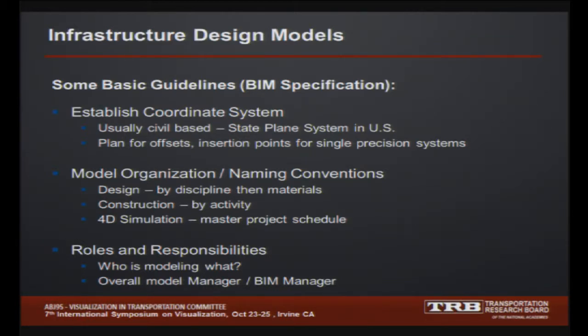Model organization is key to get established up front. Naming conventions. Is it a design model? Is it a construction model? Those have different needs and different types of naming conventions that you're going to want to establish. If it's a 4D simulation, you've got to deal with the schedule, because typically the schedule drives naming conventions. So you've got to understand who's doing the schedule and make sure they're using naming conventions up front as well. There are so many times we've gotten schedules where every activity is just form, rebar, form, pour, with no designation of the actual location or object or where it is.